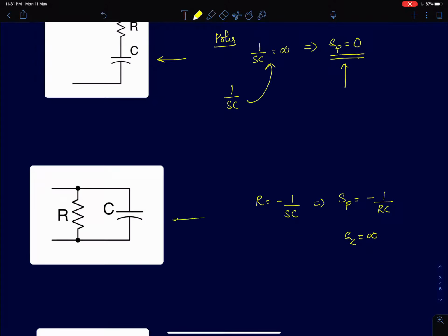Now this circuit is two impedances in parallel, R and C. Since both of them are in parallel, if you are supposed to find the poles for this circuit, then the condition that we have to use is this. One of the conditions, if you recall, is Z1 equal to Z2 equal to infinity. Both should go to infinity at the same value of S. Then we can say that is a pole. But that will never happen because the resistor is always constant. It will never blow up to infinity, if R is finite, so that condition is ruled out.